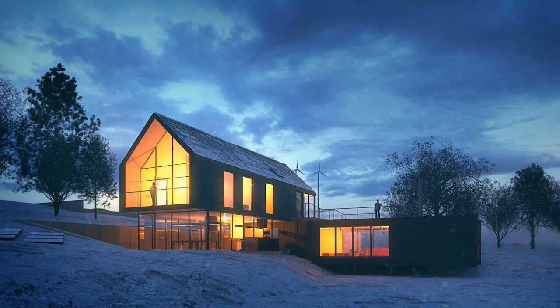So here I am back to our original image, and what I'd like to do is break this image down a little bit so that you understand behind the scenes what we've done to get here. We've done an override on the grass material with a snow material that has a texture. In this case, we're using both a snow texture that has a bump map as well as a slight displacement to it. And this, by the way, is the sample scene that ships with Revit. And this is rendered almost wholly in one pass. There's one frame in here that's post-production, and that's the snow that you see in the foreground falling from the sky, but everything else is rendered directly in V-Ray for Revit.